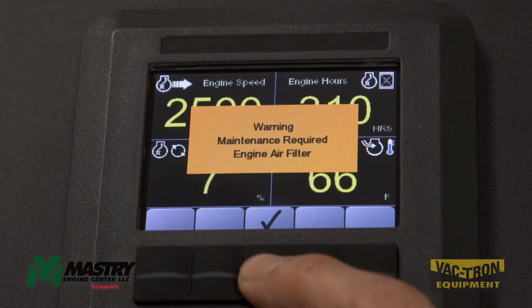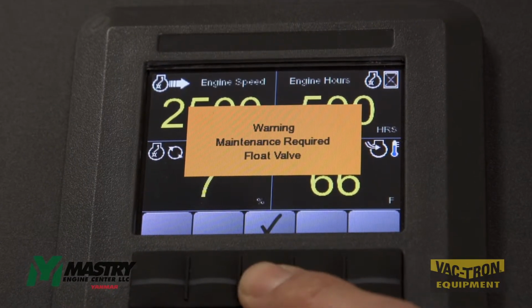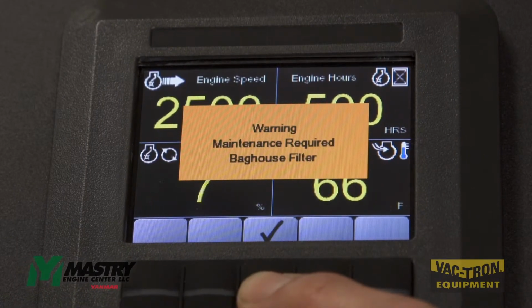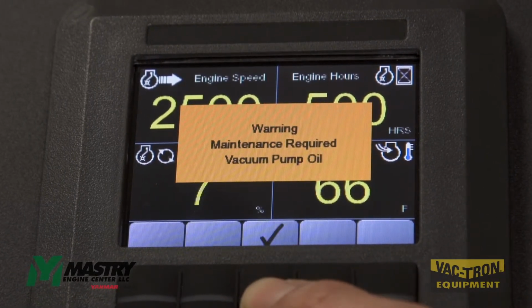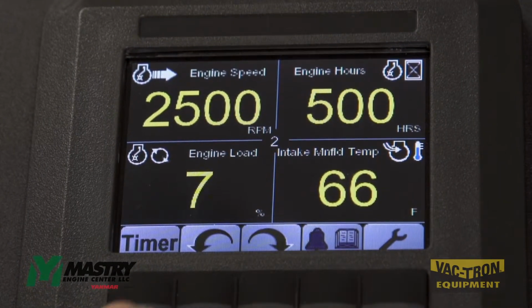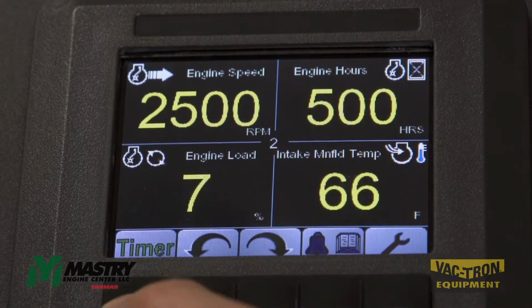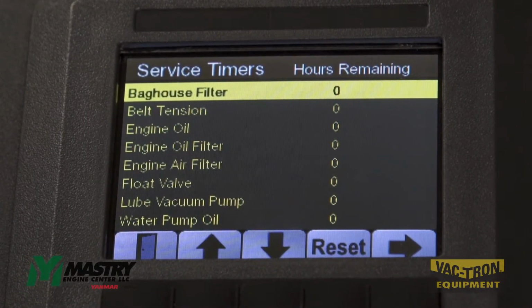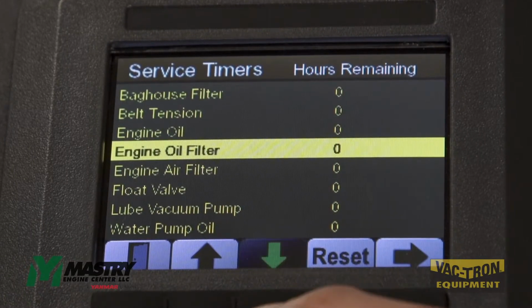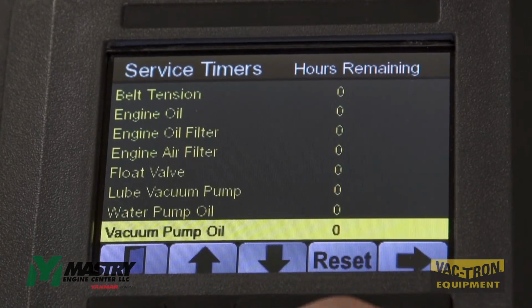To acknowledge the service timers, hit the check mark in the middle. You can see there's a variety of service timers that can pop up once the engine reaches a certain number of hours. You can acknowledge all these. And then for more information on the service timers, you can enter the timer menu and then scroll down to see the hours remaining on various timers.